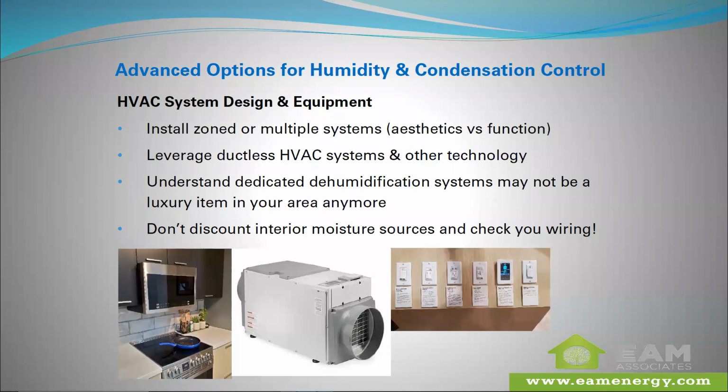They want flush headers. They want glass everywhere. There's nowhere to run ductwork effectively in a lot of cases. So you just have to be clear with people that sometimes you can't have your cake and eat it too. The home layout that you're going for is not going to work with the HVAC system that you're proposing to use. So try to leverage those ductless technologies when you can. Obviously, you can't have duct sweat if ducts don't exist.